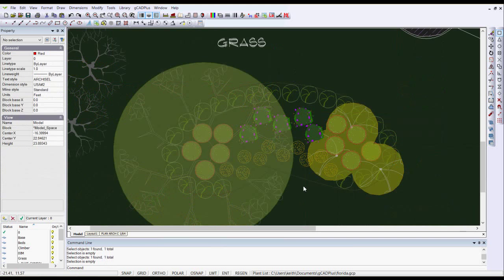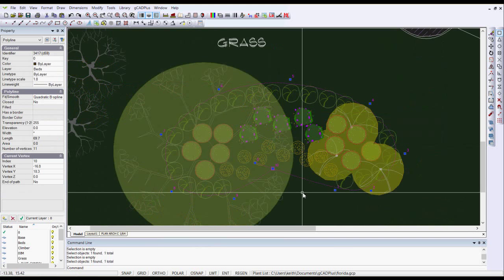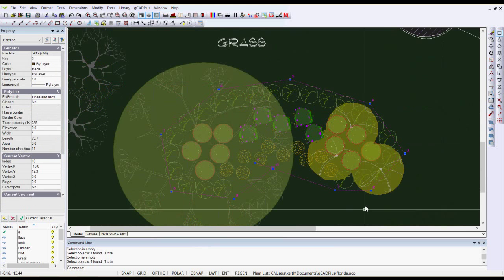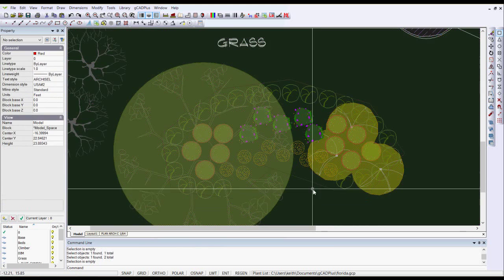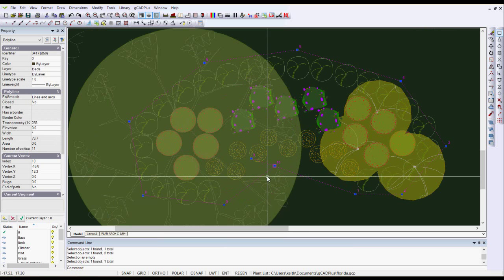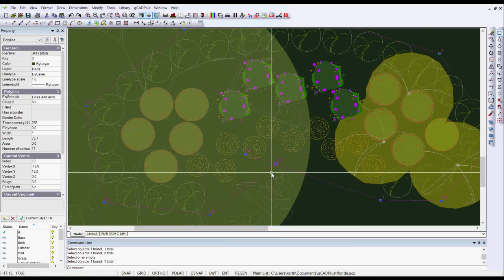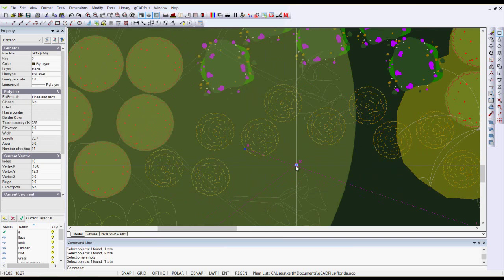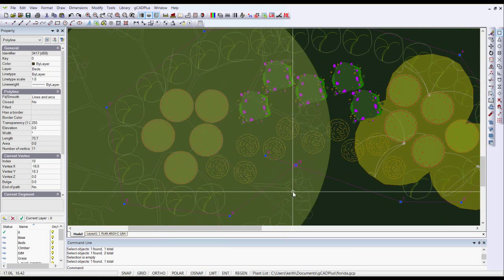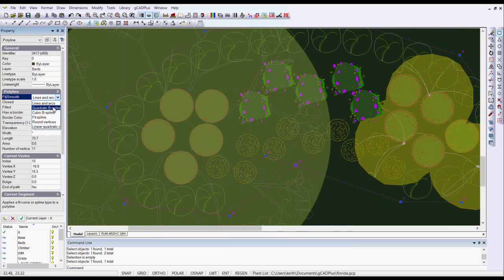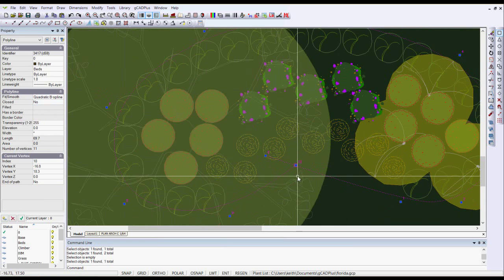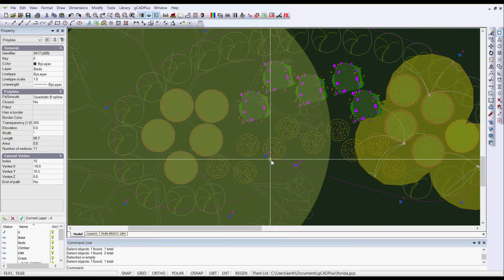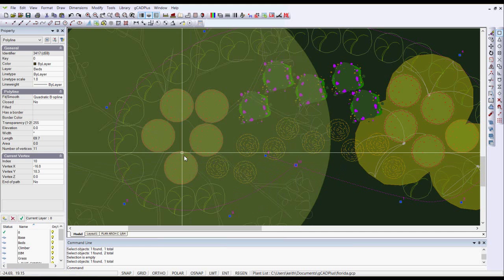Well, here is another polyline in that same drawing which has some problems. Curve fitting's been applied. Let's just take off and turn back to lines and arcs. I'll just select the polyline again. And you see, if we look at the vertices, the first vertex is here 0, and there's the last one. So it's not, in fact, a closed polyline. If we try and apply our curve fitting to it, curve fitting works reasonably well, but we're still left with this rather angular piece in the center.